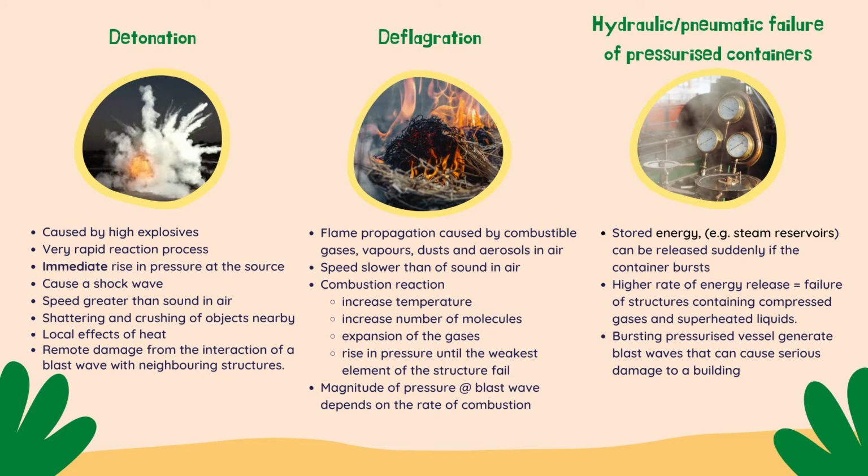Next is deflagration. A flame propagation is caused by combustible gases, vapors, dust, and aerosols of combustible liquids. These flames travel at a speed slower than the speed of sound in the air. Combustion reactions in the flame will cause a rise in temperature and an increase in the number of molecules. This causes the expansion of the gases. This expansion will cause the pressure to rise until the weakest element of that structure fails. This will relieve the pressure and allow the products of deflagration to vent to atmosphere.